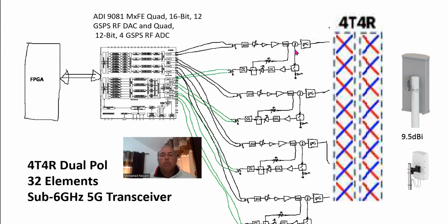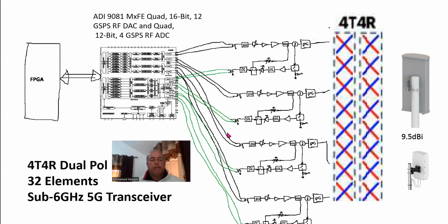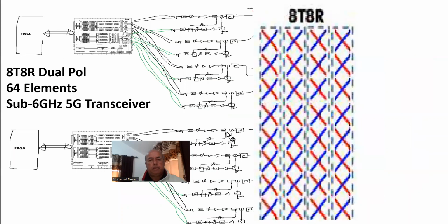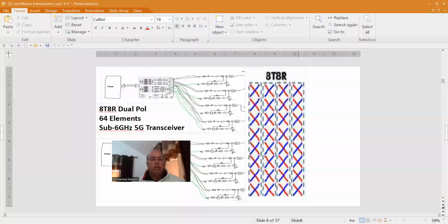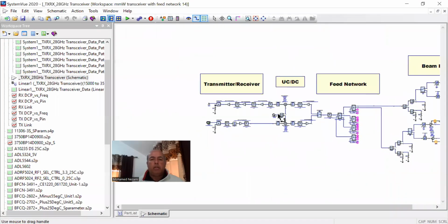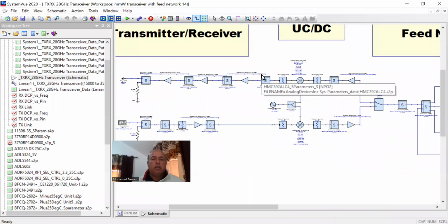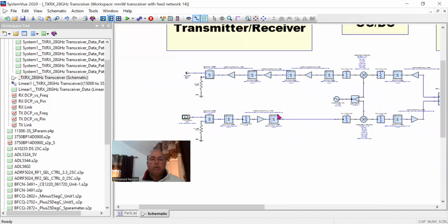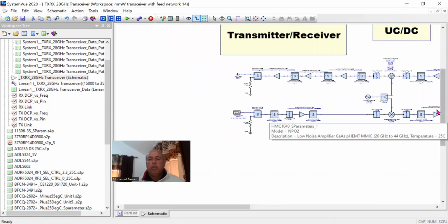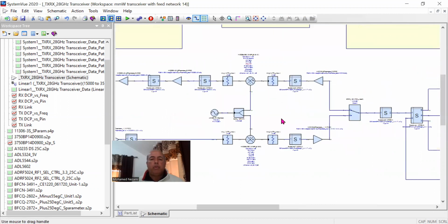Okay, so all we need is an up converter section and an amplifier case. Just so that we would, if you look at this, what I did is basically took out, recycled the first section of the sub 6 gigahertz in here. So we've got the transmit section in here, got the receive section in here. And what I added is a dual up converter and down converter. Up converter here, down converter here. And we have a synthesizer that generates the LO, okay?